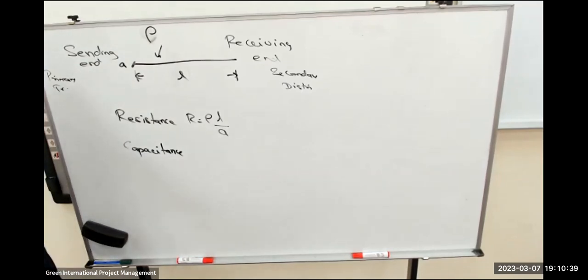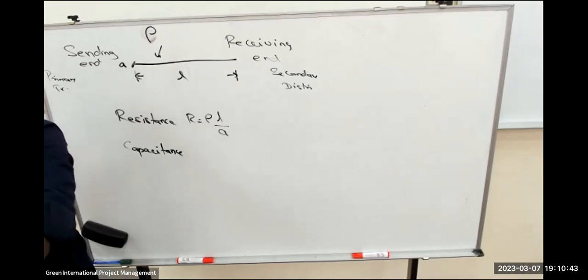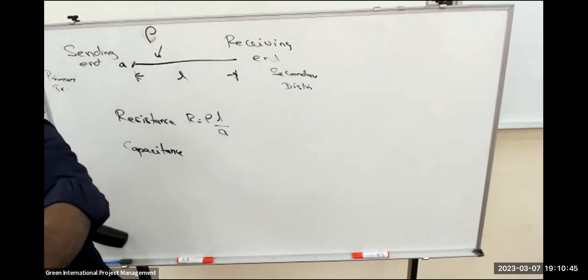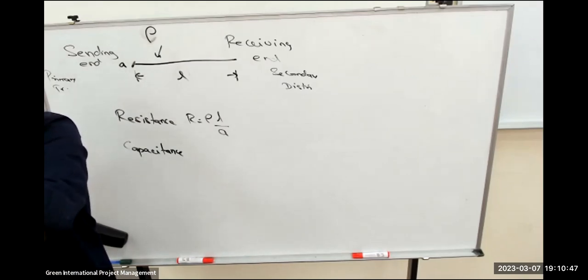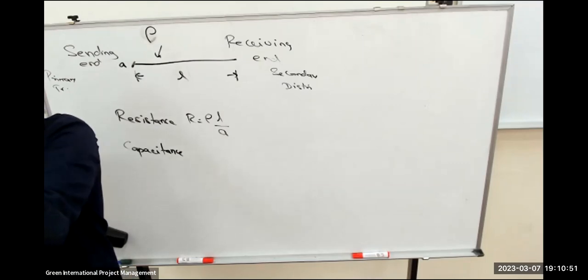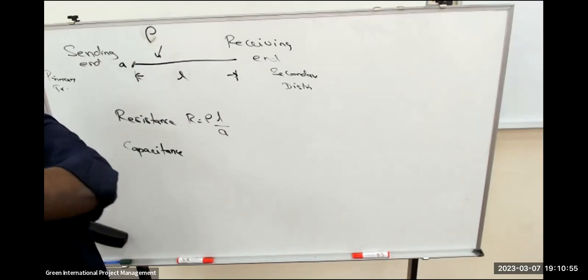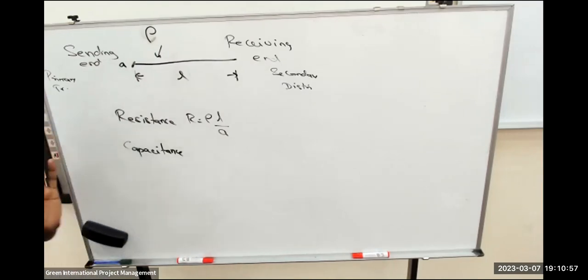At the same time, the conductor is laid on the tower, and the tower is erected in the ground. So that is the capacitance between the conductor and the ground. First I said that phase to phase we have a capacitance. Now I said that ground to conductor we have a capacitance. So in general, we have capacitance.